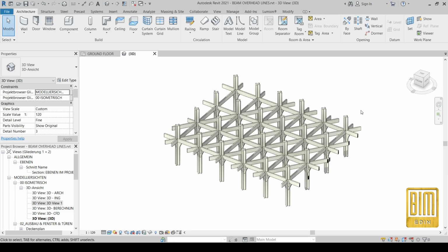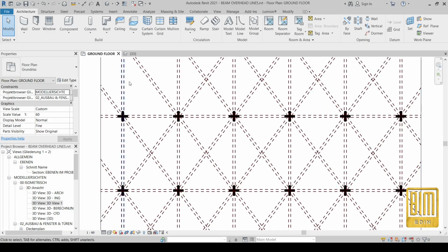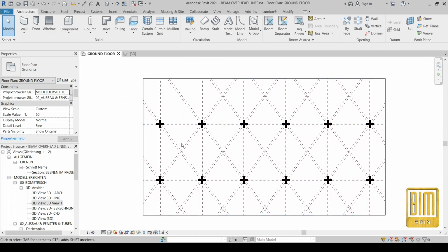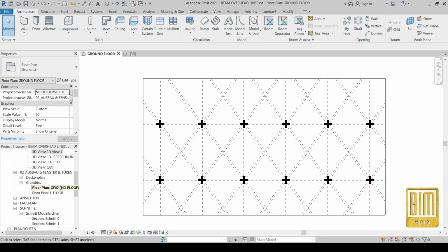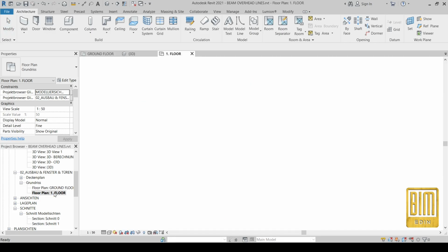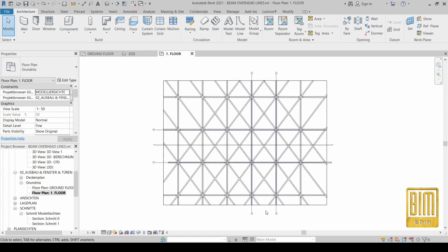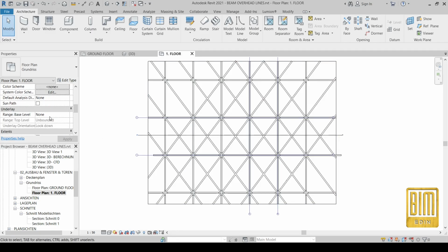Actually, while working on one of the projects, I noticed that if the cut plane intersects one of the model elements of the family, then the annotation elements of that family will also be visible, such as detail lines or fill regions, even if there is some element that covers that family. Even if the cut plane intersects the model line of the family, the result is the same. And now I will show you how this parameter works.